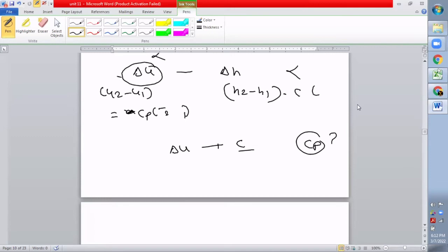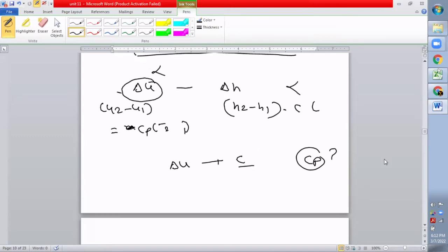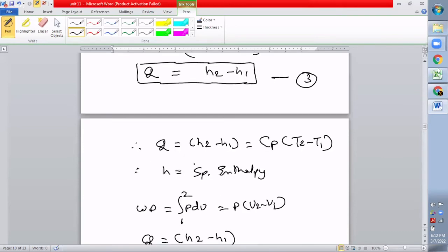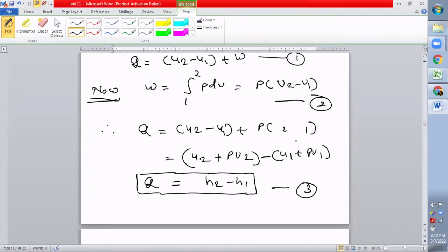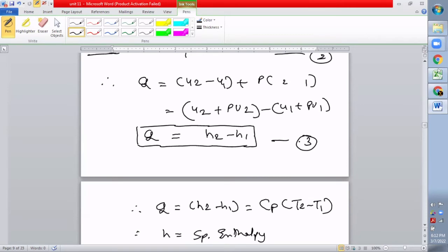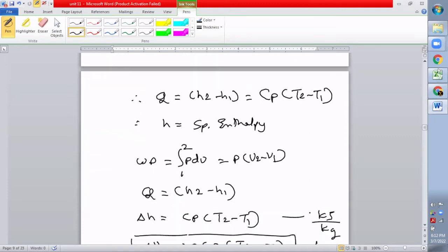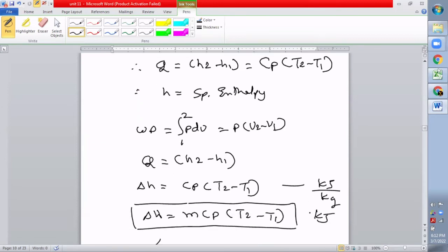Okay, del H. In this particular process, which happened at constant pressure, what is Q? Q is equal to m multiplied by C multiplied by dT. The process happened at constant pressure, so Q is equal to Cp multiplied by (T2 minus T1). If we apply the first law to this process, it is equal to the change in enthalpy, that is H2 minus H1. And because of this reason, whenever enthalpy comes into the picture, the process happens at constant pressure, and obviously volume will not be constant.